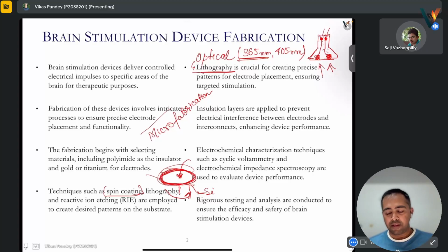Sir, from my personal experience, we made PCB boards. We took a copper sheet, put a scale and marked lines, then put it into a liquid, and only that part remained while the other part dissolved in the chemical. I think it is the same method. Yes, the same method, but at a higher resolution. We cannot make nano features that way, and since it is higher resolution, we cannot do it manually. So we are using very precise light sources, very similar to that.